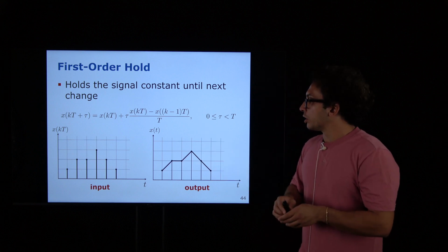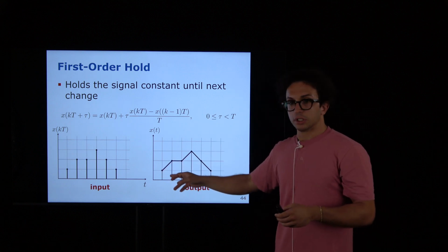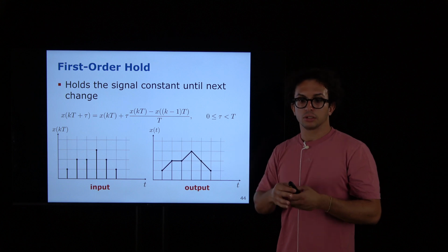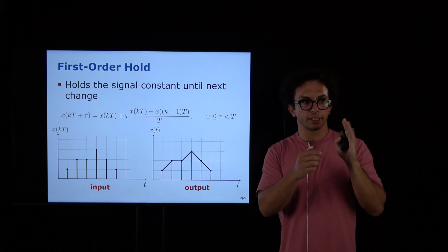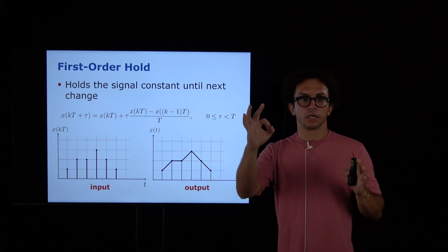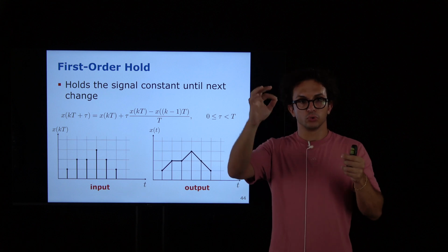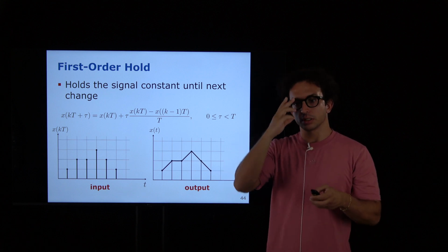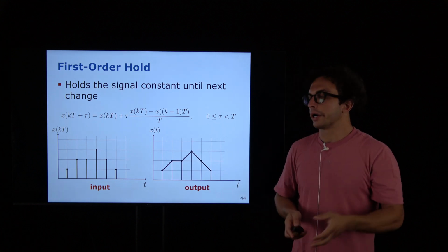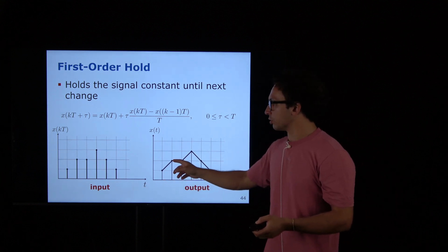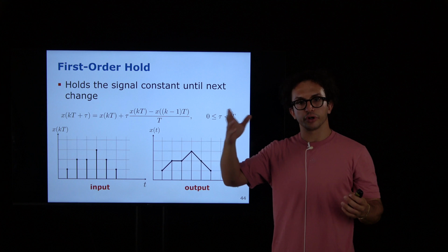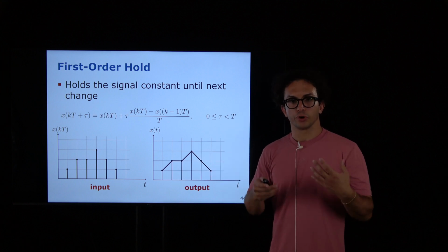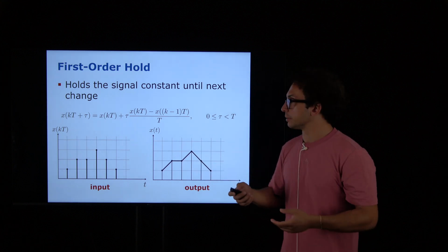This is called first order hold because it approximates with a straight line. So zero order hold is just like we take the number, so the point, and hold it. First order hold, we do the line between two points. We could go higher, so we could go maybe on a second order hold and have something which is a bit smoother and looks a bit more curvy somehow.